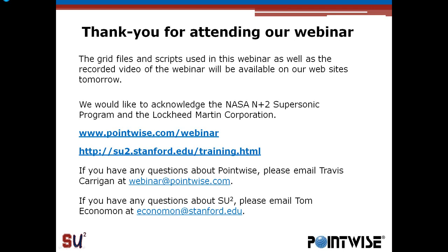The second part of the question sounded to me like you're asking how can we impose different types of design variables with the FFD control points, or how can we include more realistic or engineering-like variables. And this is one thing we didn't have time to talk about, but it is a nice feature of the FFD control points, is that you can couple those control points into engineering-like variables. So I mentioned camber and thickness. It turns out if you pick a couple of control points above and below the wing and move them together in a combined fashion, you can affect things like thickness if you move them apart. You can make it thicker. If you move them up or down together, you can affect camber.